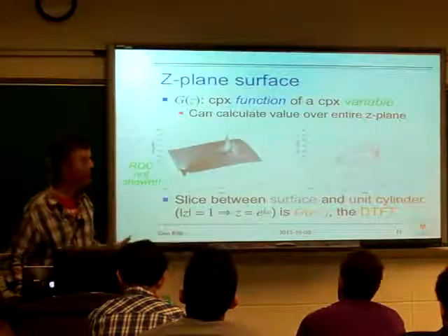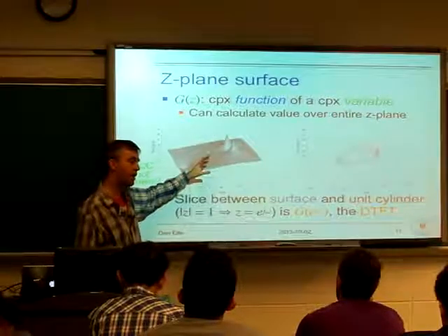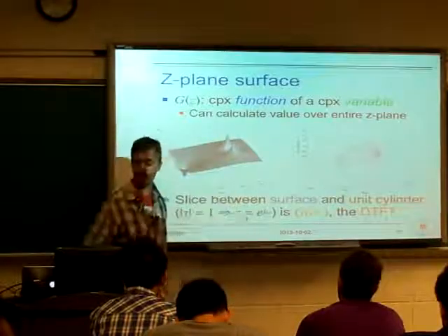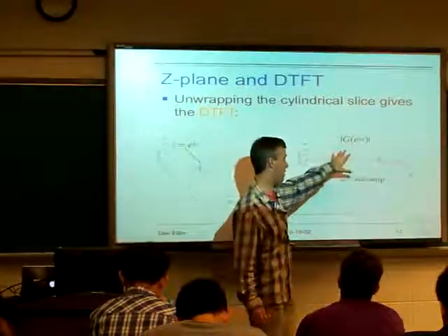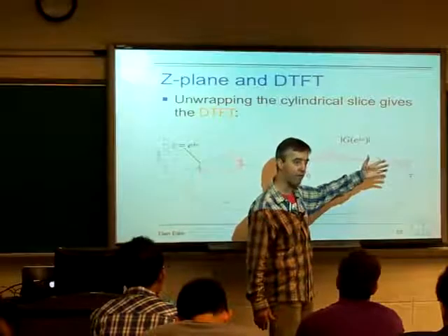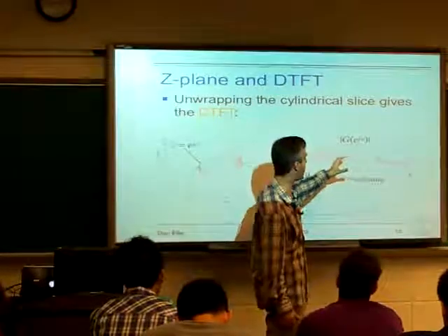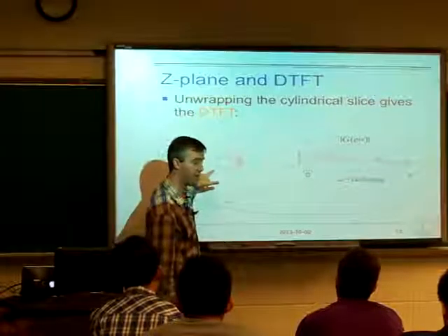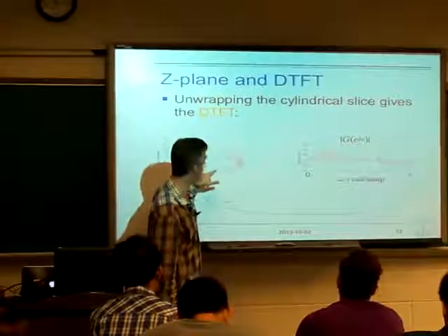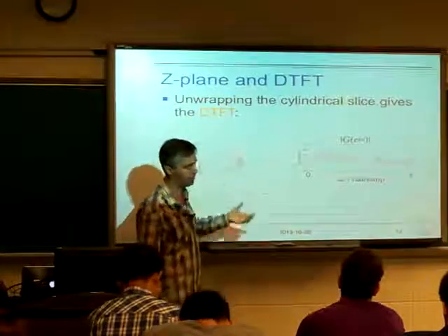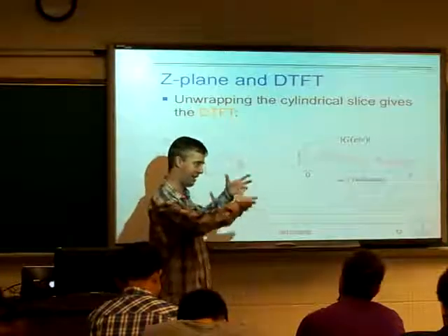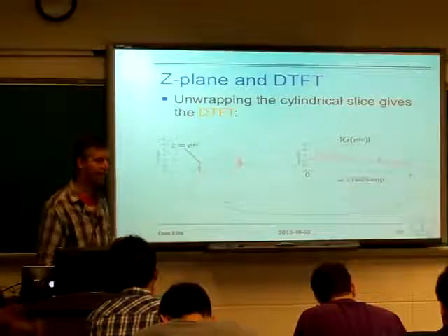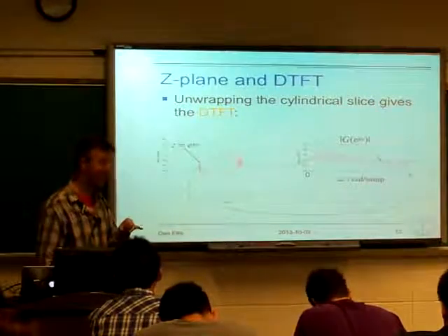And that's the real power of thinking about discrete time systems and signals in this Z-transform domain, that suddenly the features of the Fourier transform, which is very concrete, right? It's how much certain frequency components are present or how they're going to be treated. These features then relate to these fundamental properties, the roots of the Z-transform closed form expression, and they relate in a very simple and intuitive way: poles tend to lift it up and zeros tend to push it down. So that's the point, and we're going to continue to pursue that for a bit.